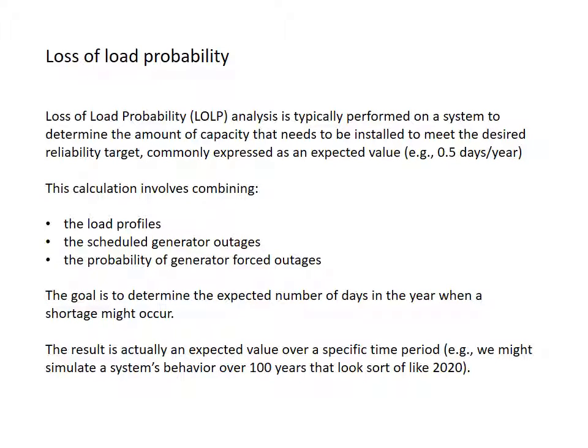So for power systems in particular, one measure of reliability. We've talked about how to think about reliability for individual system components in power systems, or you can talk about the mean time to failure, or using reliability functions for power plants. But the specific metric that system operators use to measure the reliability of power systems, one of the main ones, is called loss of load probability.